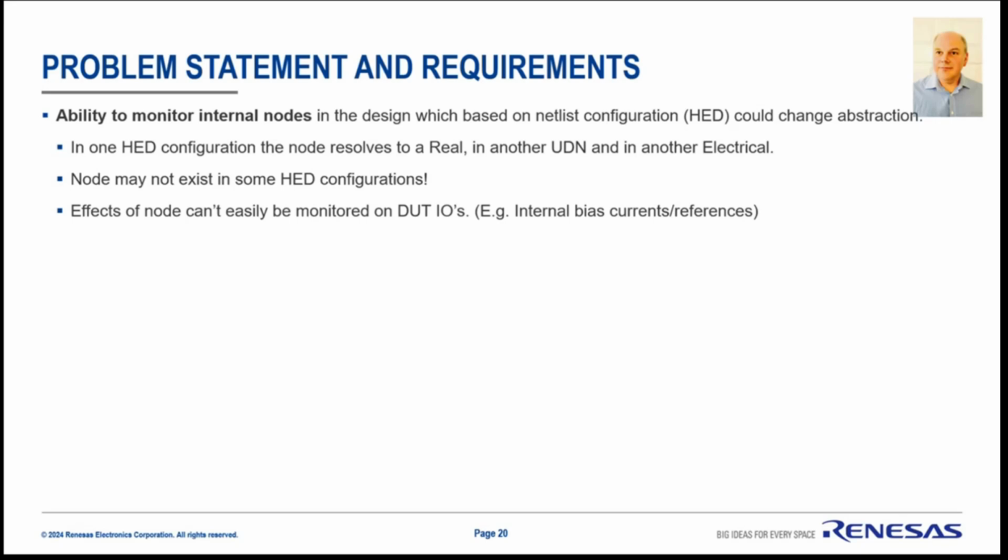Normally, from a verification point of view, you don't want to be probing too much within the design, but sometimes you can't always see the effects of subtle changes externally. So a reference voltage going to something like a DC-DC could get a big kick when the DC-DC turns on. It might then not affect any circuitry where you can look on the I/Os to notice the response, because some sort of analog filter means that you don't see it.